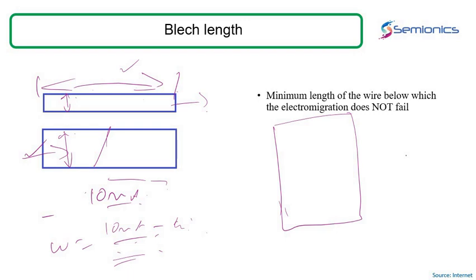Now, in lower technology nodes, if the CAD team has this utility set up, or generally if the PDK is well set, you have this feature in lots of EDA tools as well, like Cadence, Synopsys and others. We get something called an EM calculator, wherein you load the technology node and the metal stack you are trying to use, and you mention the type of metal, the length and the width of the metal. It will give you how much current it will be able to carry.